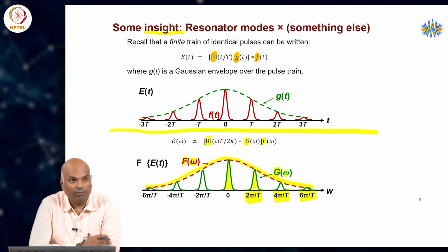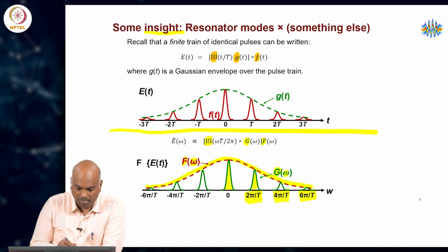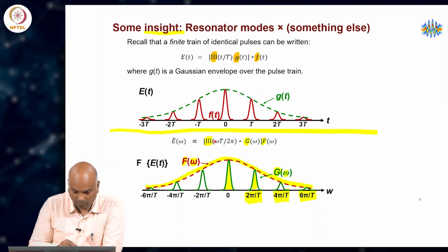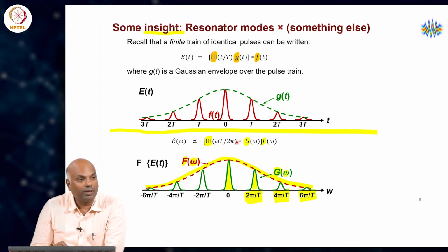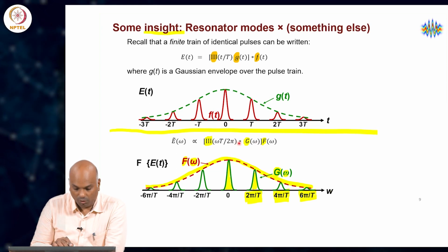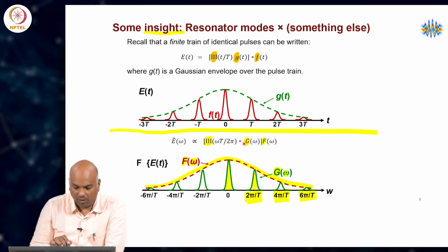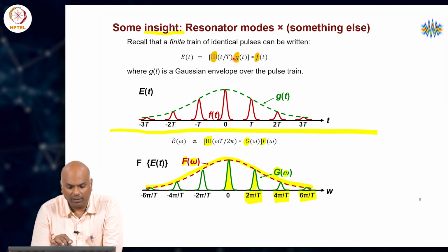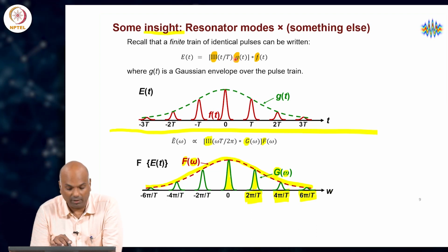Okay. So, we have not played any tricks over here, but we also note that between the periodic function and G, in the spectral domain, we had a convolution taking care of the spectral shape. That convolution between the two functions, the periodic function and G, essentially needs to be replaced by a mere multiplication in the conjugate, that is the time domain.